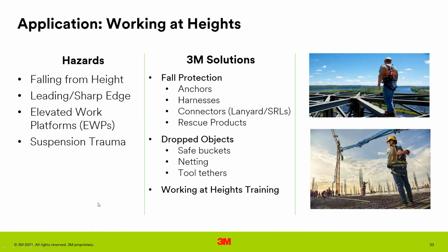So the other thing to think about is working at height. Like we said, this is the number one issue. Certainly you don't want to fall from a height, but another concern in construction is this concept of a leading or sharp edge. So if you see in this picture, I see a lot of edges here. If I fall and my lanyard contacts the side of that beam, it could potentially cut it.